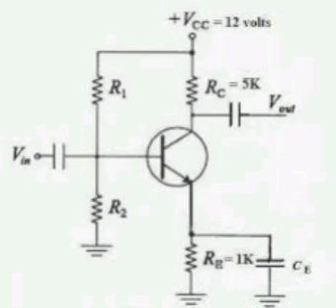K2 input of flip-flop 2 may be 0 or 1. Clear input is an asynchronous input for both FF2 and FF1, and it may be 0 or 1. FF2 is having an active low asynchronous clear input. If clear input of FF2 is 0, irrespective of W input, FF2 output is 0. If clear input of FF2 is 1, after applying W input, FF2 will follow the truth table of JK flip-flop.